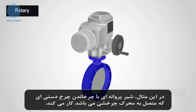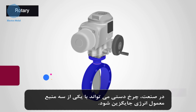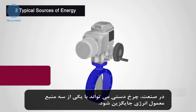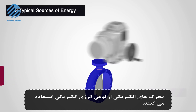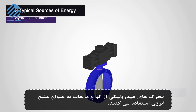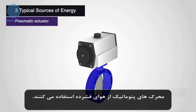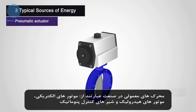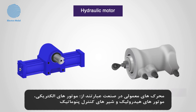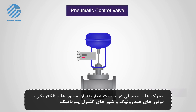In this example, the butterfly valve is operated by turning the hand wheel connected to the rotary actuator. In industrial applications, the hand wheel could be replaced by one of three typical sources of energy, which can operate the rotary actuator. Electric actuators use some form of electric energy to operate. Hydraulic actuators use a variety of liquids as a source of energy. Pneumatic actuators are operated by compressed air. Typical actuators in the industry include electric motors, hydraulic motors, and pneumatic control valves.